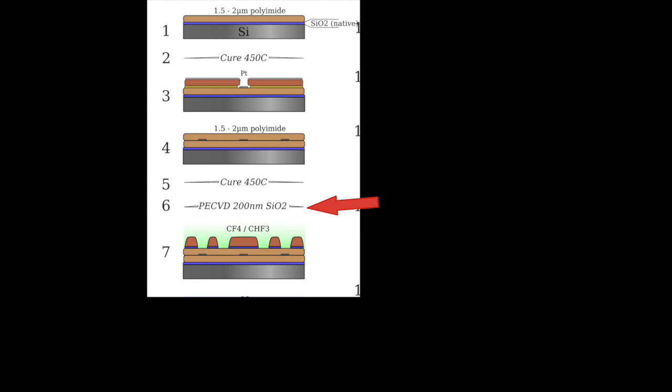The silicon dioxide layer is applied via electron cyclotron resonance. In this figure, this is referred to as plasma-enhanced chemical vapor deposition. What a mouthful. This process, as I understand it, works by pumping gaseous forms of silicon and oxygen into a vacuum chamber and then energizing these precursors by generating magnetic fields which ionize the gases into a plasma, rather than using a high temperature or ion bombardment.